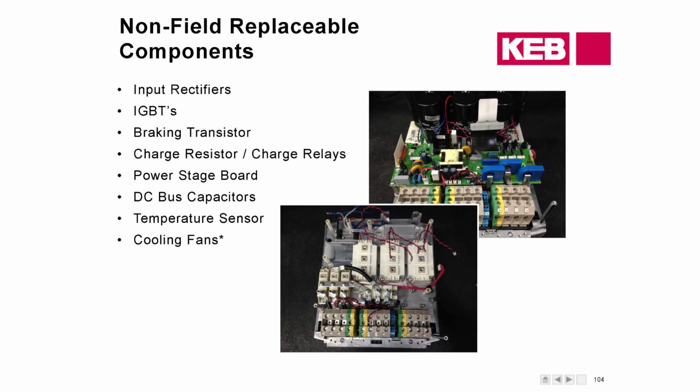All right, non-field replaceable components. These are things that you're going to have to send to KEB, and we're going to have to take a look at. These are the input rectifiers, the IGBTs, DC bus capacitors, the power stage board itself, temperature sensors, charge resistor, charge relay. I have fans on there. The fans you can replace in the field if you wish.